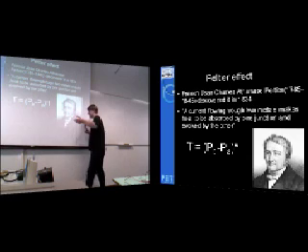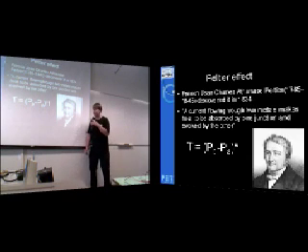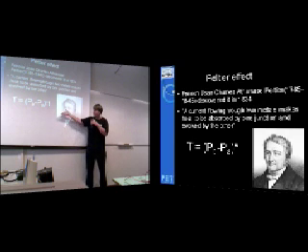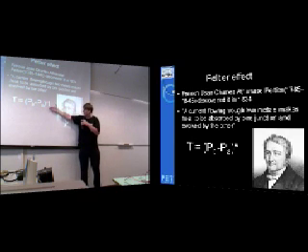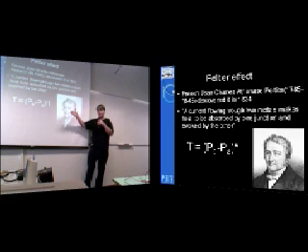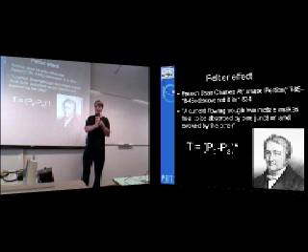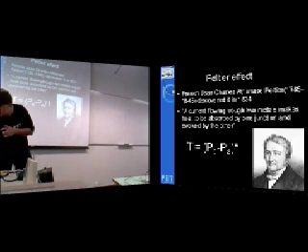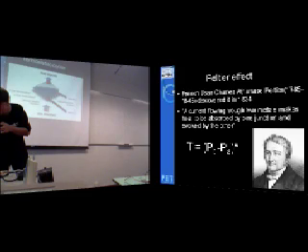So if this current right here is inverted, the temperature potential is inverted too. So it will make one side cool and the other side hot. And if we swap the wires, it will make the first side hot and the other side cool. So let's come back to that.